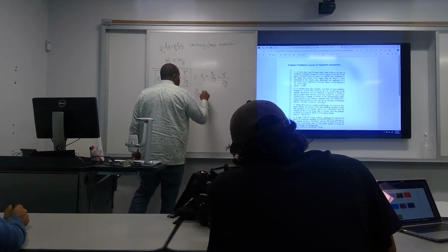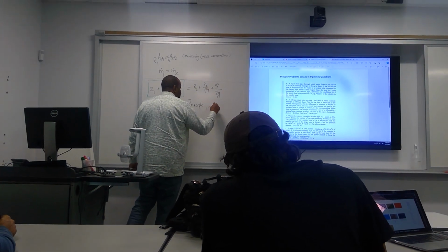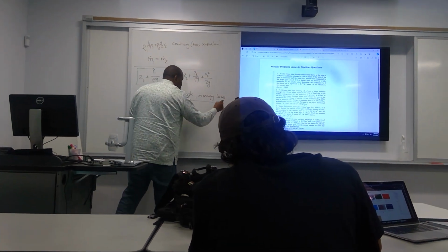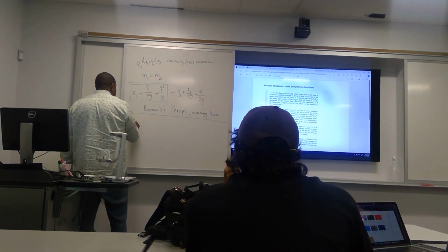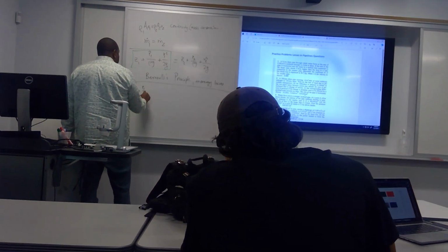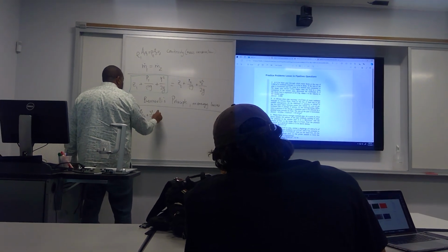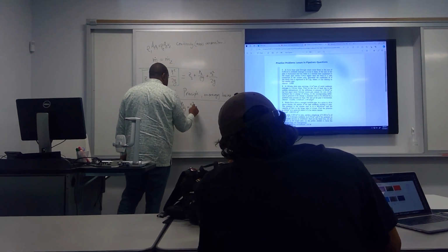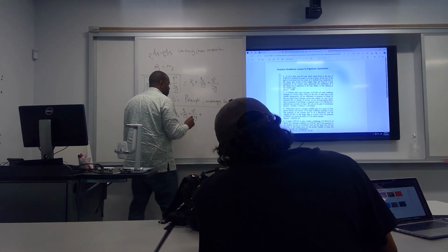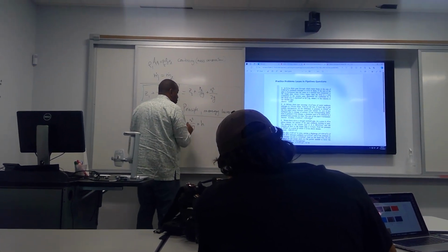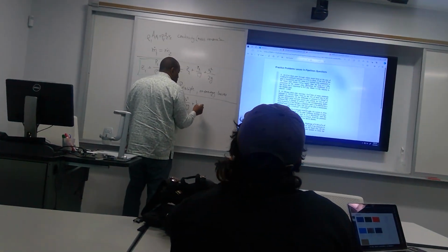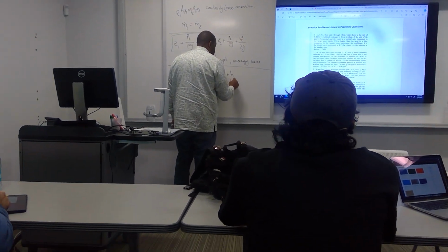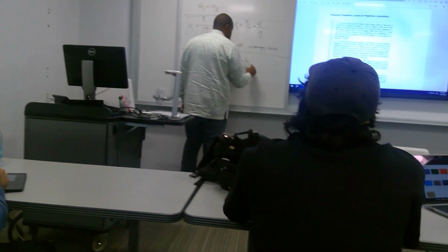We don't have any energy loss here. We're assuming no losses. But when we look at pipelines, we can also have P1 over rho g plus V1 squared on 2g equals P2 over rho g plus V2 squared on 2g, plus our losses, which you can call H or HL, our shock losses, plus HF.